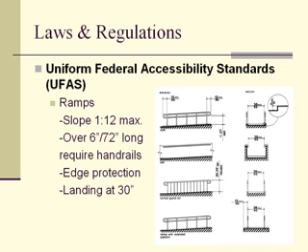And there are some diagrams, as you can see. The height of the handrails should be, and there are some differences, but UFAS specifically requires that the height be mounted between 30 to 34 inches above the finished floor to the top of the gripping surface.